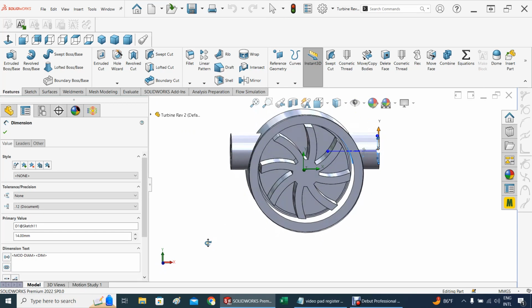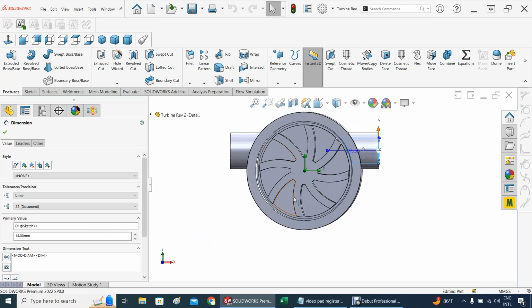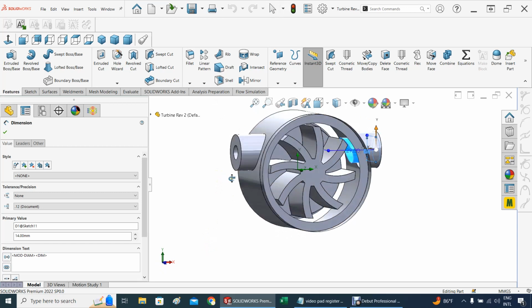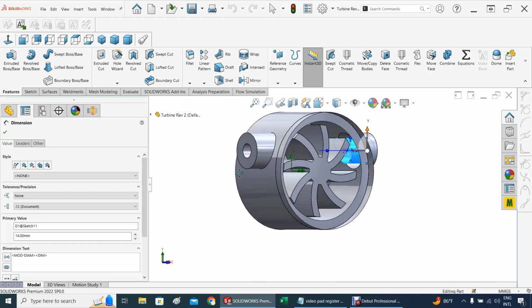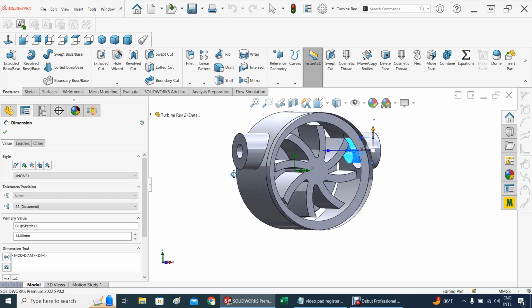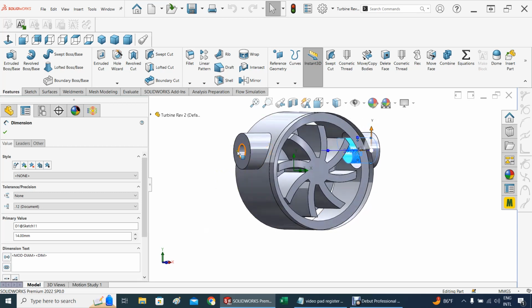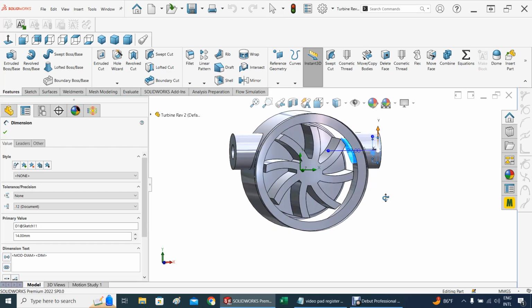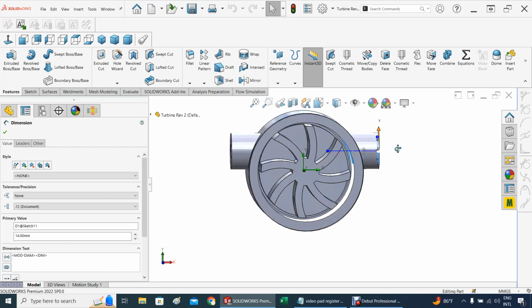So basically this is going to be run with water. Again, it's a small turbine. I don't expect obviously to power the house with this, and the flow rate is tiny. It's about 1.5 gallons per minute getting in at the aqueduct pressure, which will be about, I don't know, 40 psi. So 40 psi getting in and moving the turbine, and the question is how much energy can you extract out of it. And the flow rate again is 1.5 GPM. So that's the main idea.